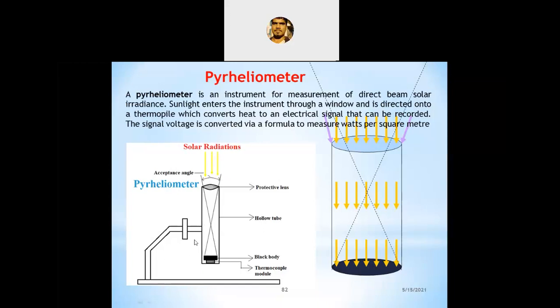Once both strips attain the same temperature, one strip is heated by solar radiation and the other is heated electrically or artificially. Once both strips are heated, that is thermal equilibrium, or steady state, where both are at identical temperature, and the energy used for heating is equal to the absorbed solar energy.